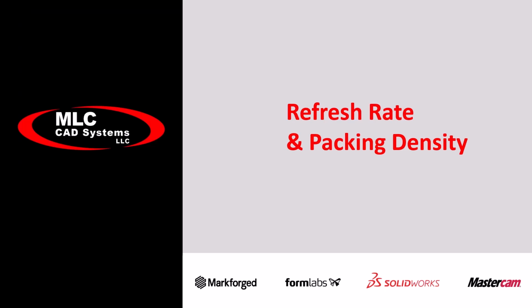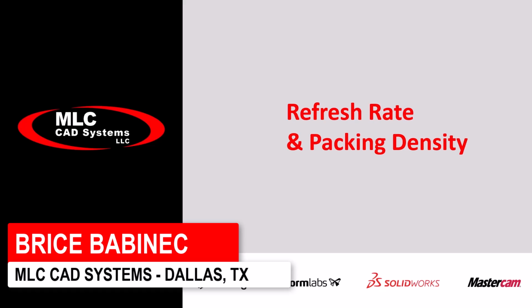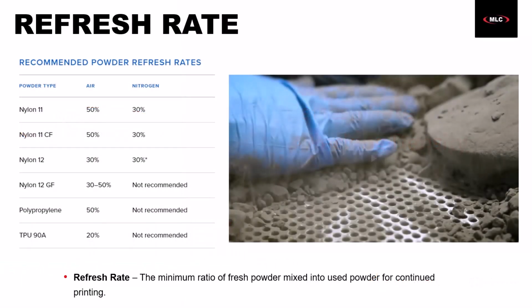All right, so let's finally discuss packing density and refresh rates, because this is where you really start to maximize your cost per part when it comes to SLS. So we touched on this earlier, but to recap, refresh rate is the minimum ratio of fresh powder that's mixed into used powder for continued printing and to retain the material's mechanical properties.